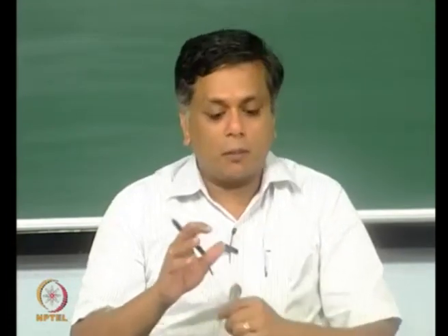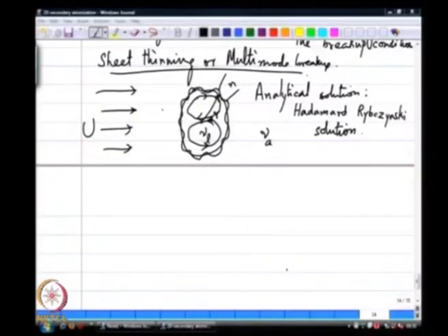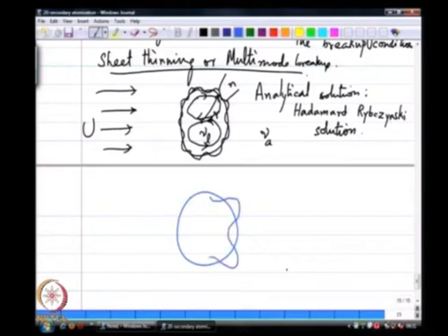What that means is that if I subject this drop to a cross flow, I have a certain number of waves that will preferentially grow on this drop, and as they grow I might have this wave grow and eventually pinch out a drop from the side that corresponds to this wave number.